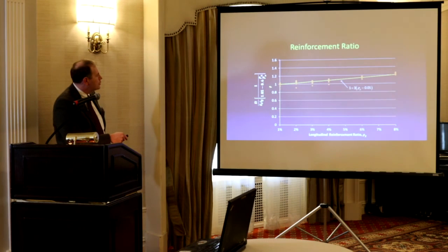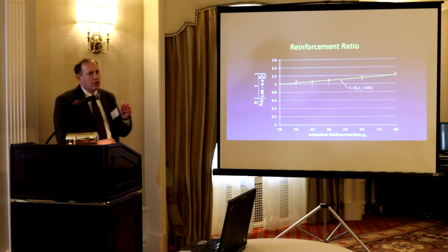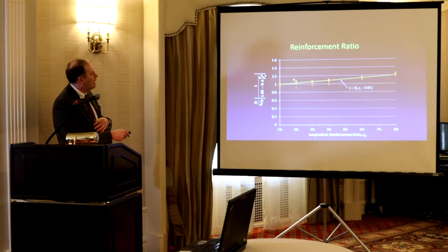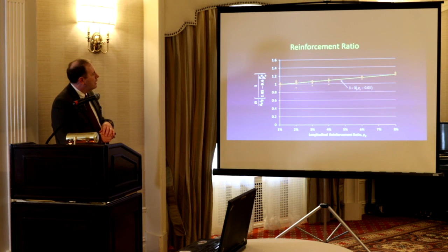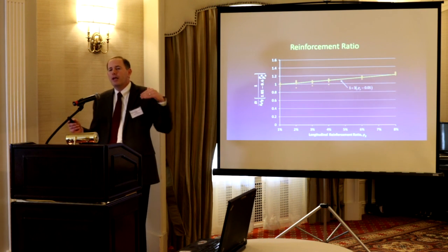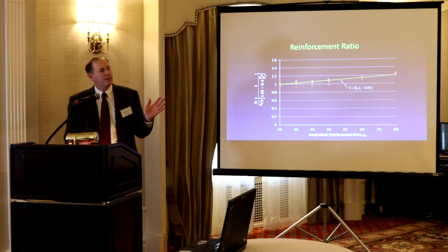So it turns out with the steel, what you're seeing is a range here that's happening. This is because we're looking all the way from low axial loads all the way to very high. So at the low axial load we're here, and as the axial load goes up, we may have a little bit of reduced stiffness, but we're picking this up across here. And so this little line could represent how much steel you have in a column. Again, from 1 to 4, I'm looking here, I can call it 1. I don't need to even use a line. I can call it 1 and there's no variation. If we want to account for it, we can.